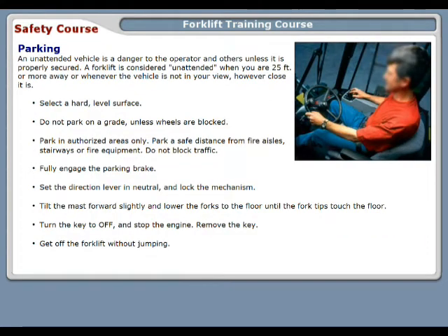An unattended forklift is a danger to the operator and others unless it's properly secured. A forklift is considered unattended when you are 25 feet or more away, or whenever the forklift is not in your view, however close it is. Always select a hard, level surface. Don't park on a grade unless the wheels are blocked. Park in authorized areas only.